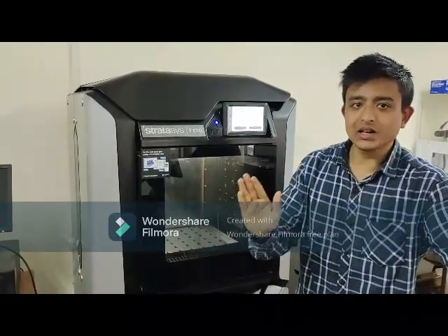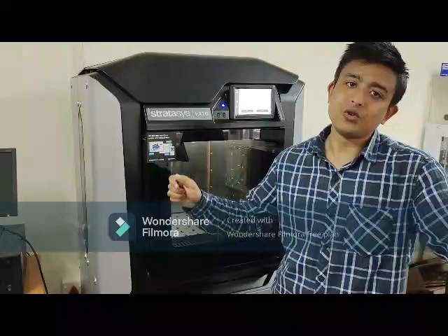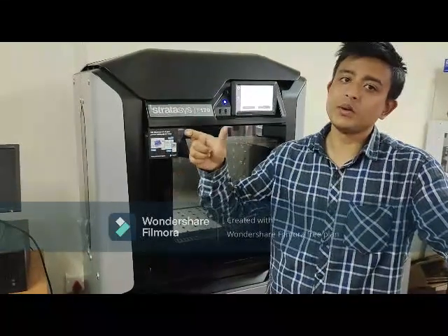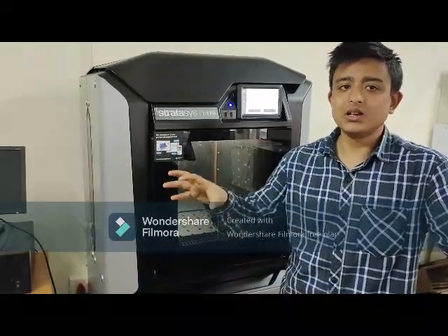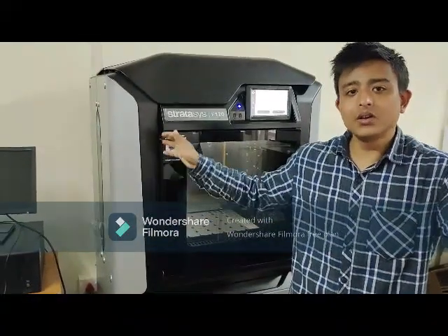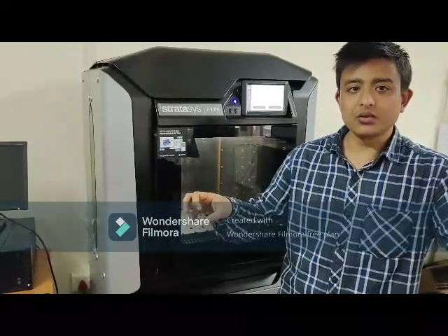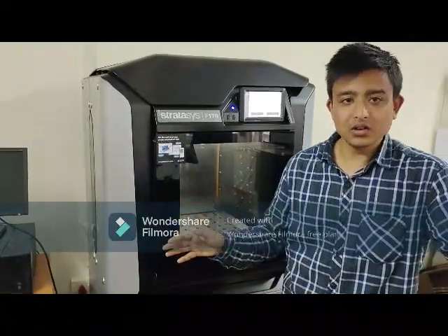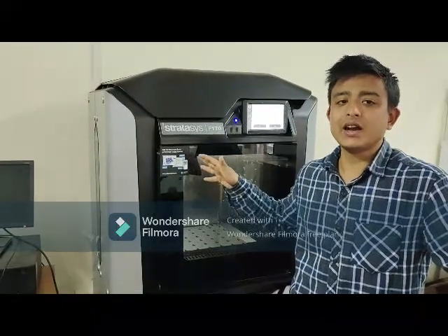At a particular time, what should be the X direction movement, Y direction movement, and Z direction movement, the machine knows. For the first layer, the last layer, or the middle section, where the nozzle head should be, it already calculates, because it is extracting the geometric codes from the CAD model we give to the machine. After the extraction of the geometric codes, it knows what to do and what not.